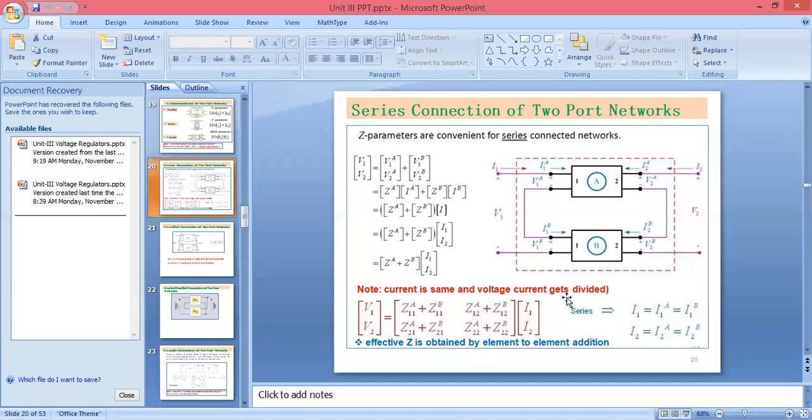Now we are supposed to calculate the equations for voltage for these series connections. Here we are studying how two-port networks are connected. If there are Z parameters, we can connect the network in series combinations. If there is the concept of admittance, we can connect Y parameters in parallel. And if there is ABCD, which we call the transmission parameter, we can connect these in cascade format.